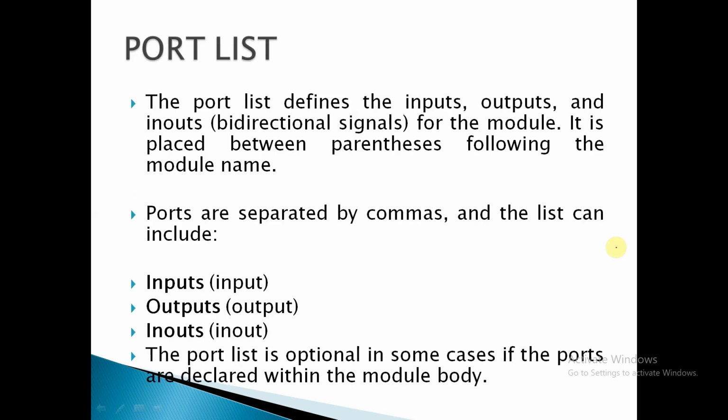Coming to the port list, which I said already, we have different types of keywords for mentioning the ports. One is the input keyword for mentioning input ports, the output keyword for mentioning output ports, and the inout keyword for mentioning inout ports. Okay, and the port list is also optional in some cases, if the ports are declared within the module body.